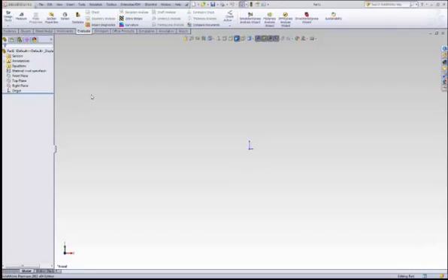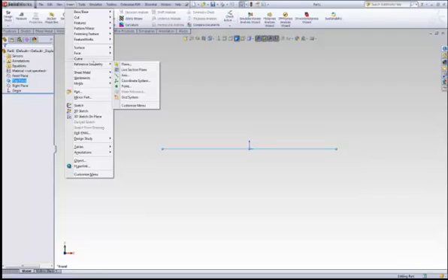When creating weldments, your weldment is going to be based on a skeleton, and that skeleton can be 2D sketches, or it could be 3D sketches. The new functionality that I'm going to show is a grid. So I'm just going to create a 2D object and use the grid option in 2011. We'll choose this top plane to begin. Under the Insert pull-down and Reference Geometry is a new icon. It's called Grid System. And this does have a button, so if you use it a lot, you can add it to your shortcut toolbar.